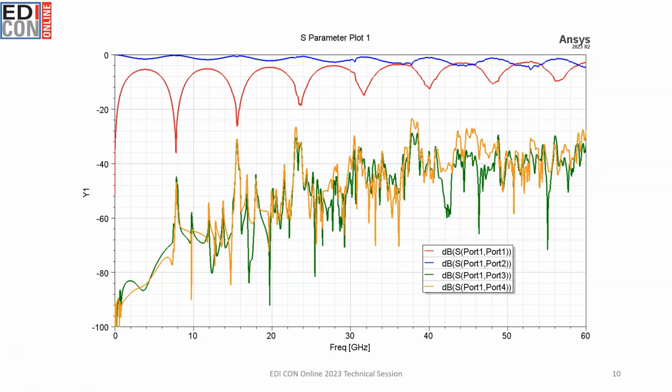The crosstalk is reasonably low once you get into the 10 to 20 gigahertz range. However, once you get into higher frequencies, you can see that it starts to rise above negative 30 dB at several frequencies. So the first place to start to improve this channel is to look at the vias and the pads. As I mentioned earlier, vias and pads are really going to dominate this return loss dominated behavior in short channels. So if we then go and cycle back into a third-party application, we can look at the vias and pads, or we could optimize these in Ansys.